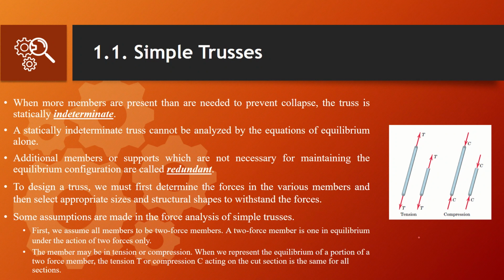Now, these forces in effect are treated as loads externally applied to the pin joint connections. Accounting for the weight of a member in this way gives the correct result of an average tension or compression along the member, but this will not account for the effect of bending of the member.